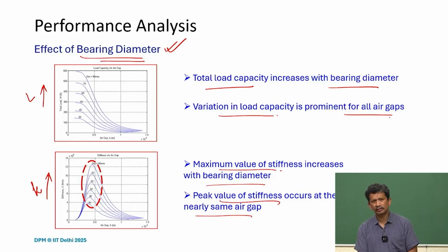What we also need to understand, like in the case of supply pressure, is whether it is possible to increase it further. There are other kinds of problems, and they are mainly related to fluid dynamics. As we increase the pressure, these elements or the bearings are prone to instability, and usually it's called pneumatic hammer. This is mainly because of the squeeze film damping effect.